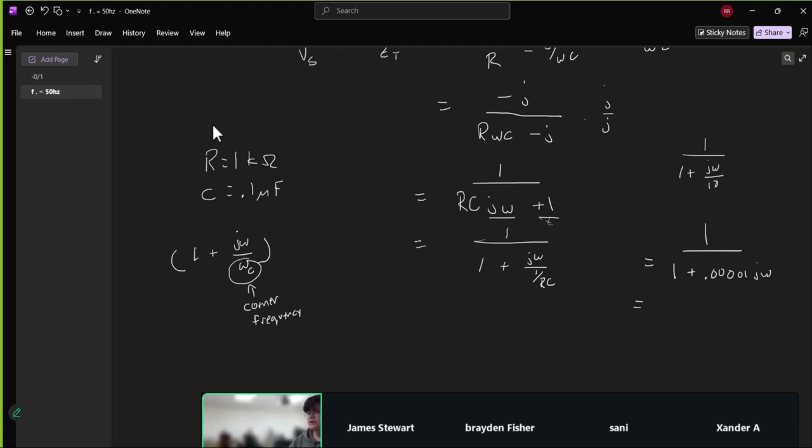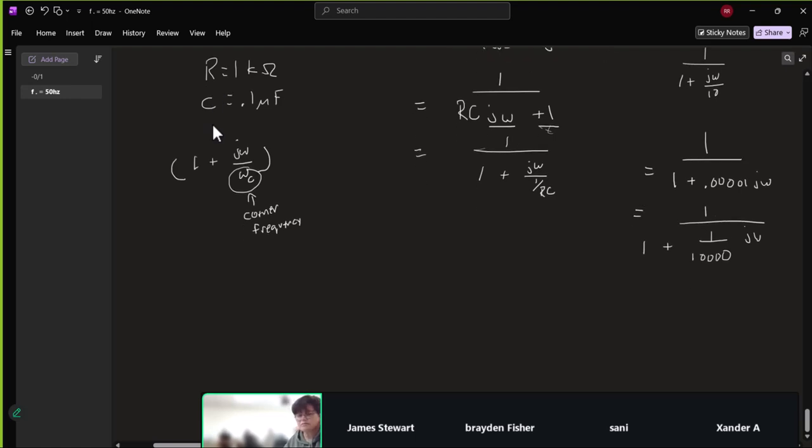And 0.0001 is 1 over 10,000. So this is 1 over 1 plus j omega over 10,000. So that tells us our corner frequency is 10,000.